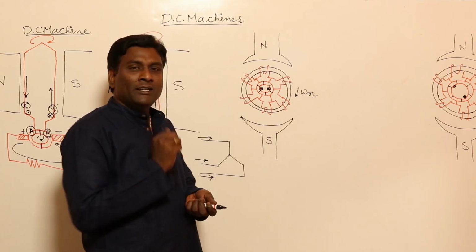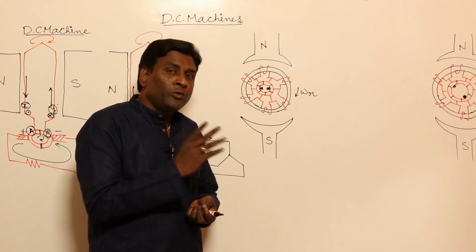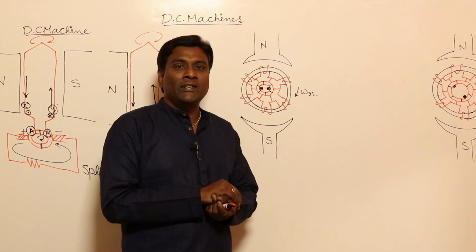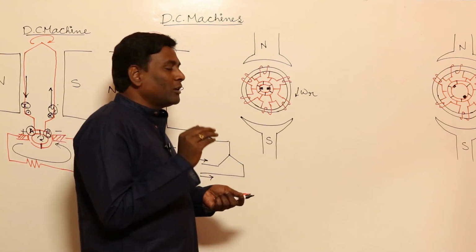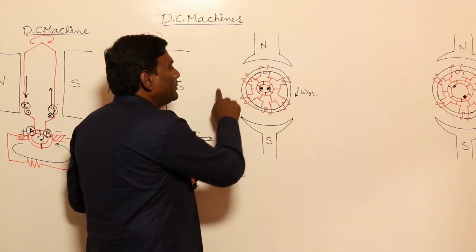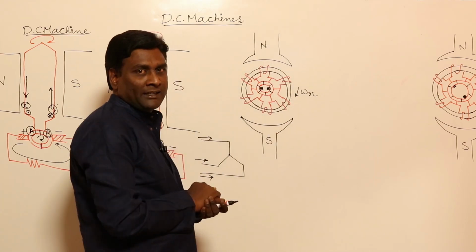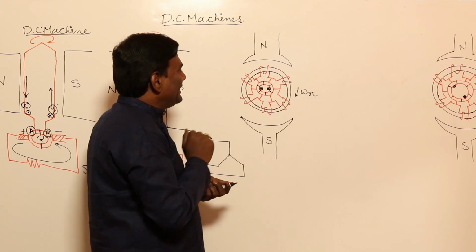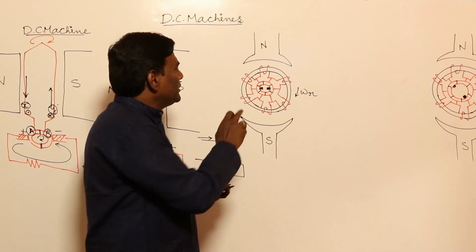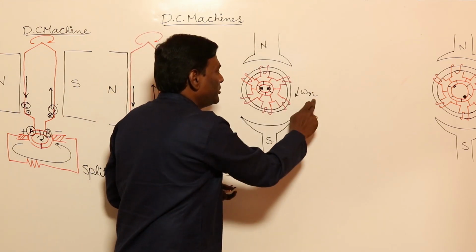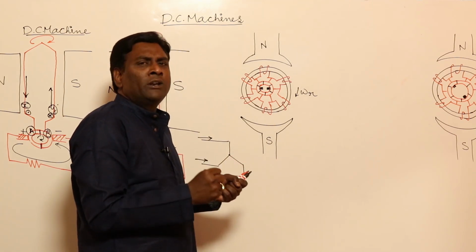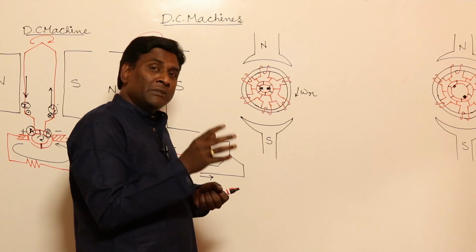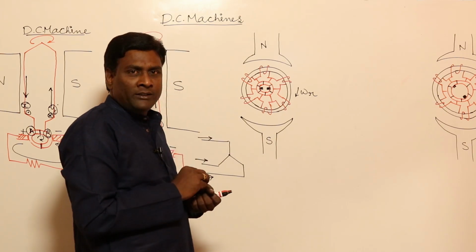Now coming to the DC machine, why should we have closed winding only? Why can't we have open winding? In order to discuss that, let me take ring winding. In ring winding, if you think of sinusoidal flux density distribution, in the alternator we struggled a lot to keep the flux density wave better sinusoidal.